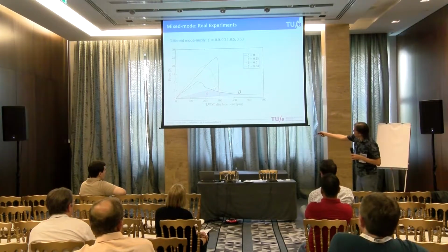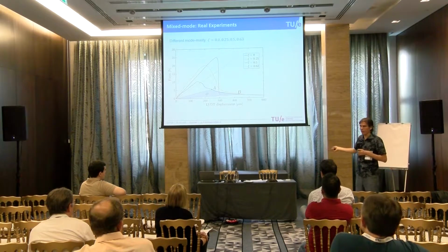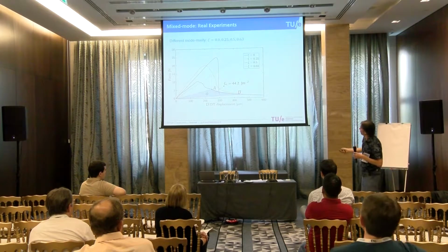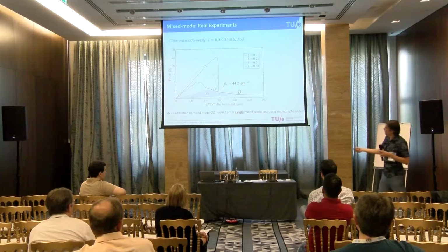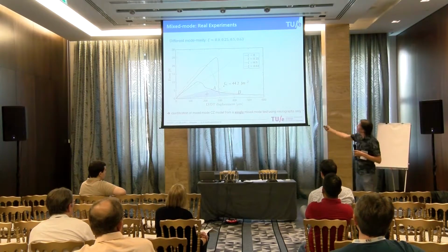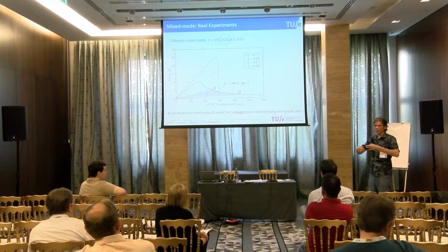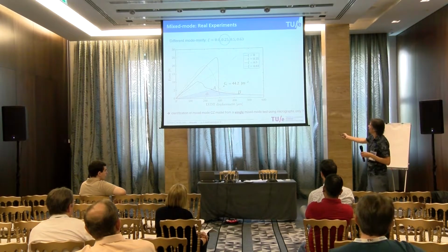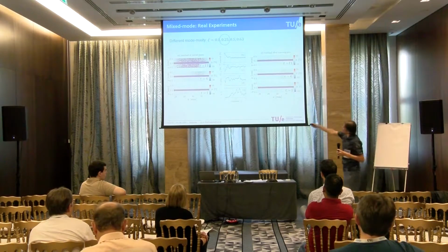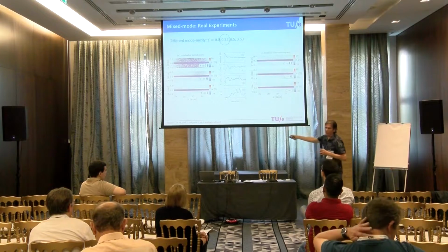We also can actually, in mode 1, just look at the area under the curve and get a fracture toughness, so we can compare with that. And that's, in this case, 44 for this particular specimen. The idea again is, can we have a single test to identify this? We're using this test now at a slightly lower mode mixity, but still knowing that inside the process zone there's all this mode mixity. Experimentally, this is at the initial guess, we have again